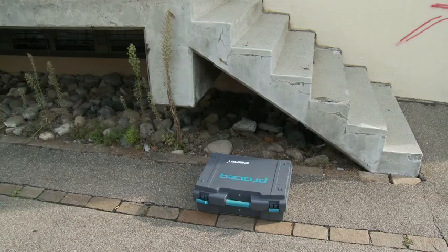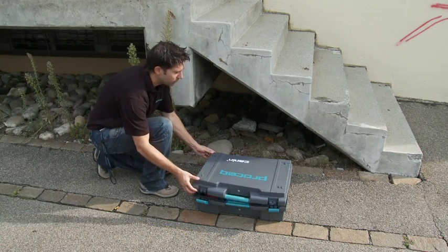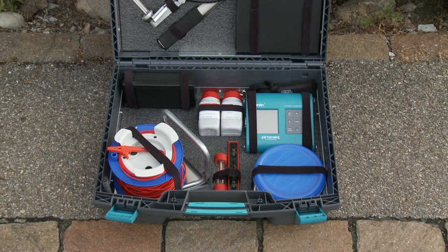Getting started. Here we can see the complete Canin instrument. An indicating device for display and data storage, a rod electrode which is a copper sulfate half cell, a one-wheel electrode, a 4-point Wenner probe including the control plate, a 25-meter cable for connecting to the rebar, 250 grams of copper sulfate for the electrodes, 250 grams of citric acid for maintenance purposes, and a box with electrode cables and spare parts.